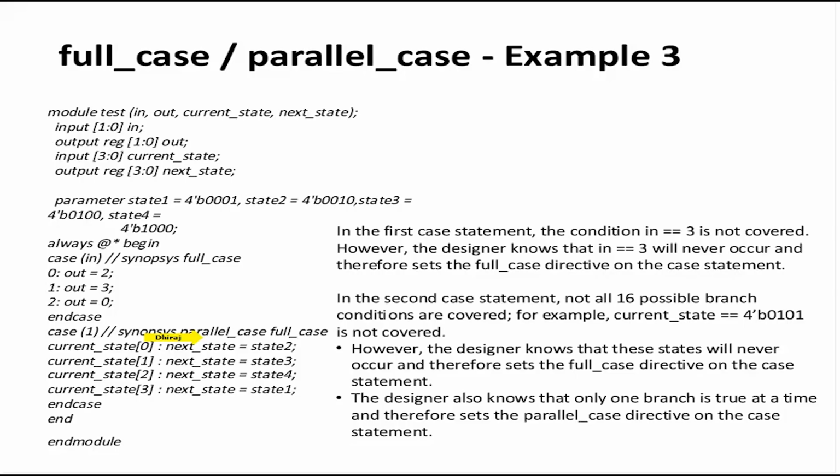Because in this case, the designer knows very well that these cases are invalid, they will never occur, and so his simulation test cases also don't have these cases, so he never faces a problem of simulation synthesis mismatch. But again, the important thing is that the designer should know what he's doing.